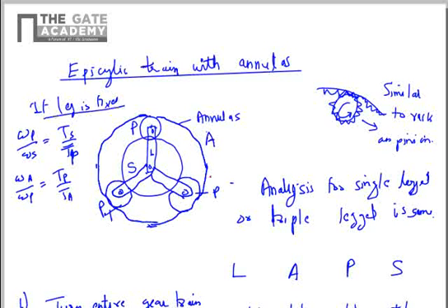But usually you will want the sun to be fixed or the annulus to be fixed. We have seen the derivation for the sun to be fixed. In the case the sun is fixed, we will get omega L by omega P equal to 1 plus TA by TB in that case.